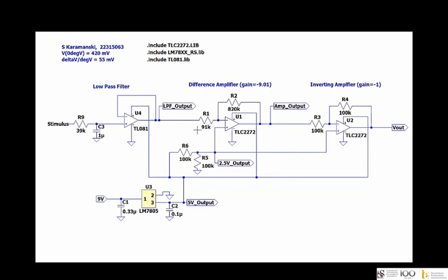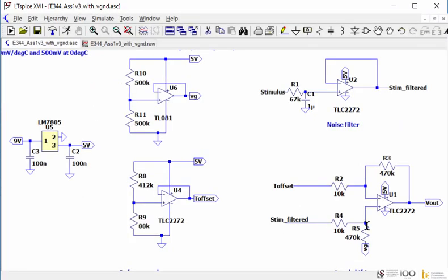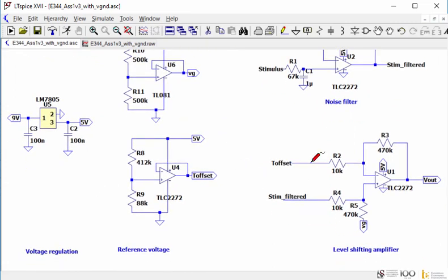Yeah, and if you didn't have the op-amp at the top there, it would have affected the filter performance. R1 would have affected R9 and C3, and then also the gain would have been affected. The R1, R2 gain would have been affected by R9 and C3. Right, the same goes for T offset.